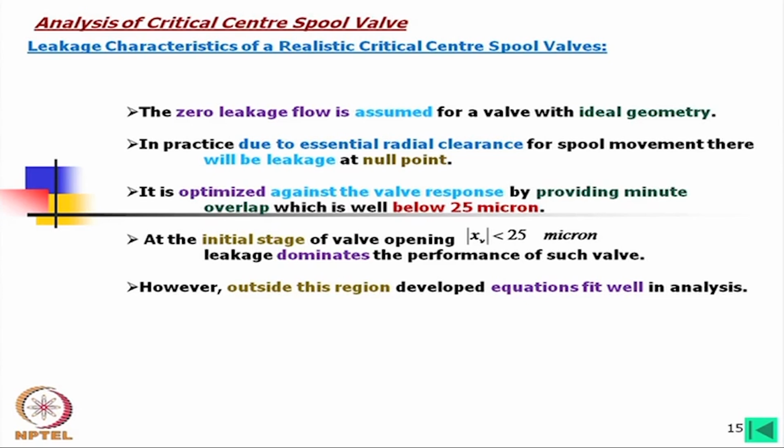It is not again linear, the diameter and this, you can see this area is very big. And for a very large valve, again this full port opening is not very desired, because there will be a very high change in flow rates with a small stroke length. So, there we go for partial ports. For a small valve, full port. For a large valve, you will find the partial ports are there. Again it is rectangular due to this linearity. W is a constant, either it is pi ds or maybe some angle into diameter of the land.